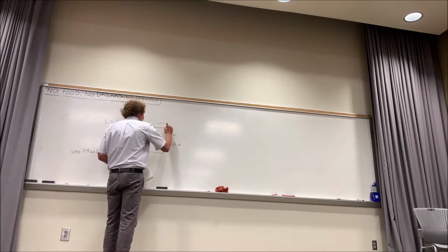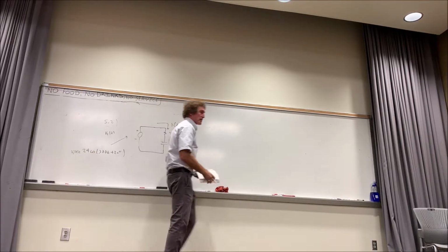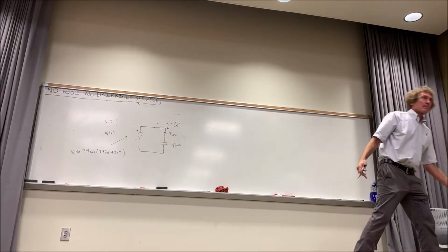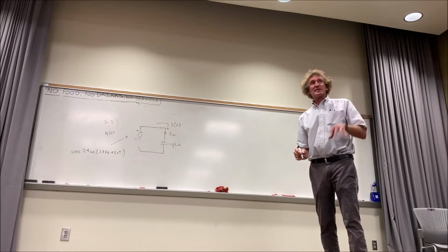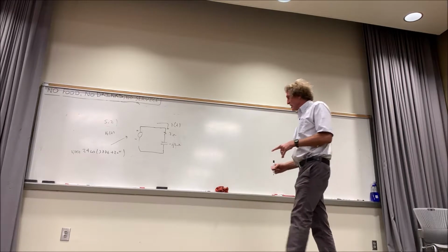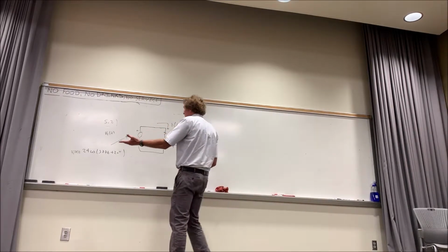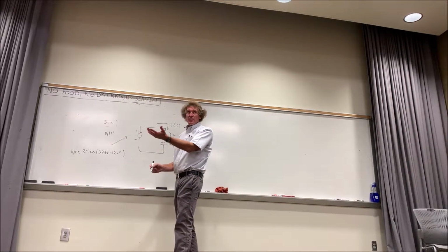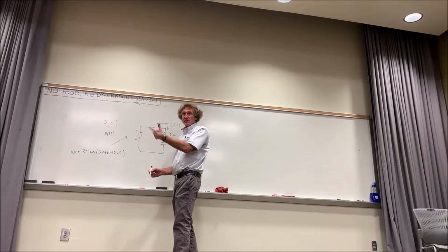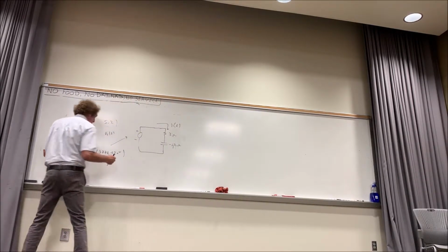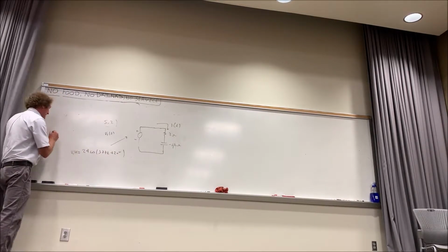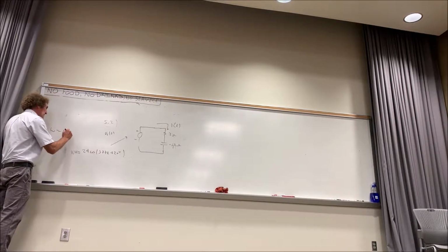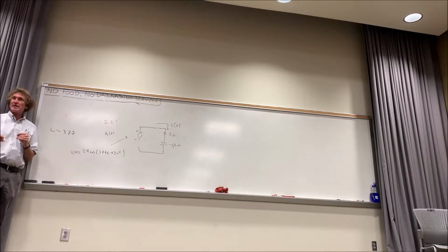And he wants i(t). I'm going to show you how to do this quickly. Listen, the way you do this, don't write differential equations. Turn this circuit into its equivalent phasor domain circuitry. If I have 24 with this argument, omega here is 377 radians per second.